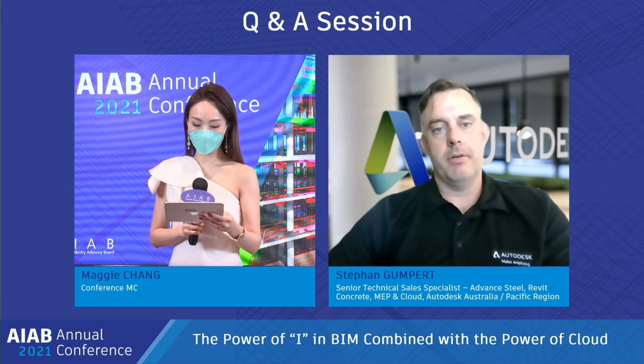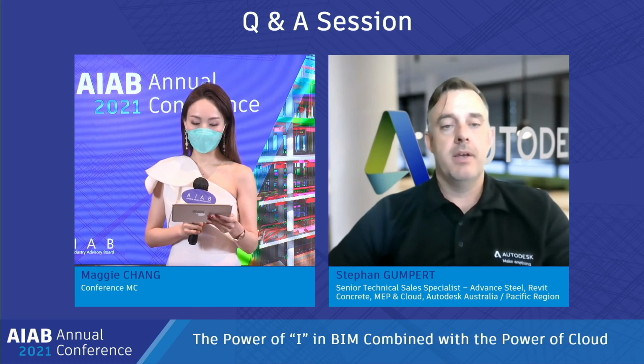She asked, what has been a recent example of where the transfer of data from design to fabrication occurred? Sure, it's a good question. Recently I had a plumbing company come to me who were wanting to change the way they do their plumbing assemblies out on site. So rather than developing their plumbing assemblies and cutting material out on site, this customer was looking to take the design, turn them into as-built fabrication assemblies inside the design space, build the assemblies in the workshop, and then transport these assemblies out to site, which meant that the pre-lay was much more efficient out on site.